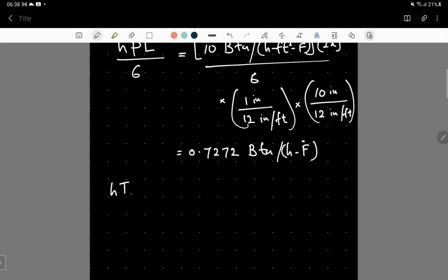It's a contribution from the free stream convection, which is open at the surface on the right hand side, which we can write down as h times T infinity times the perimeter times the length of the element, with h being 10 British thermal units per hour feet squared Fahrenheit degree